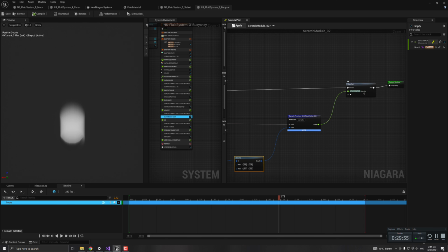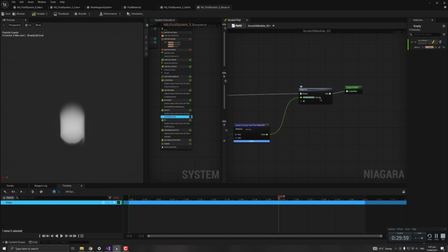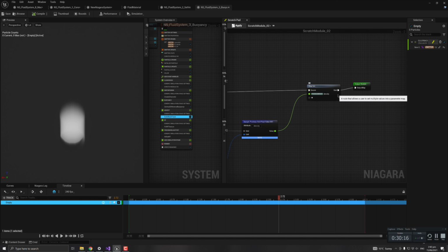And one thing that's nice about Niagara is that it takes care of the source and target grids for you. You might have noticed that I've not had to create any source grid and target grid and swap between them when we advect. That's all taken care of for you behind the scenes. But that does have some implications for performance, which we'll see in a bit soon, because the more channels you add, there can be a performance effect on that. So I'll talk about that soon.